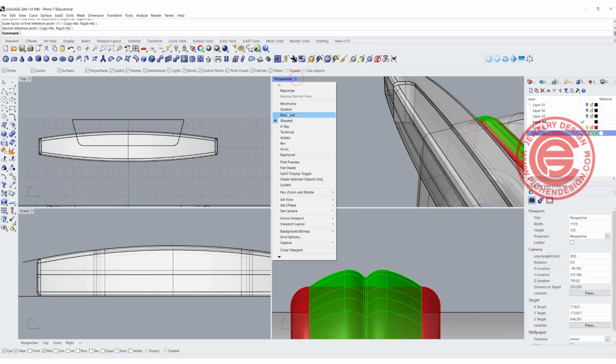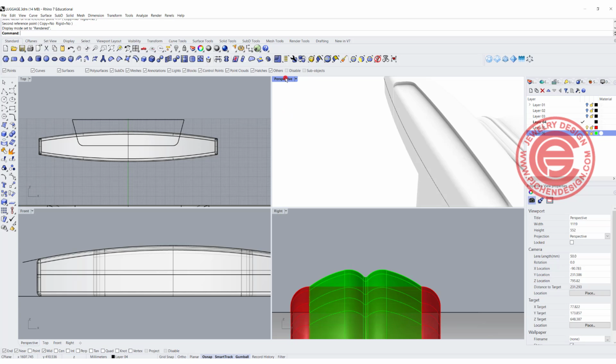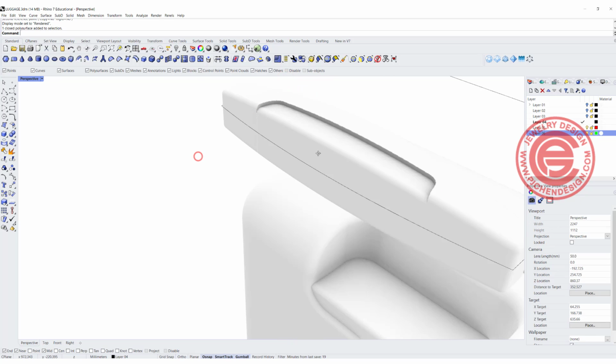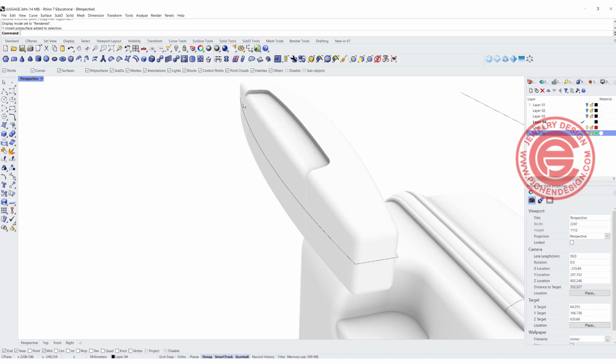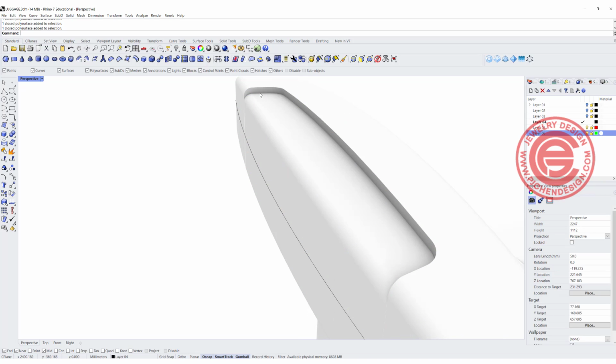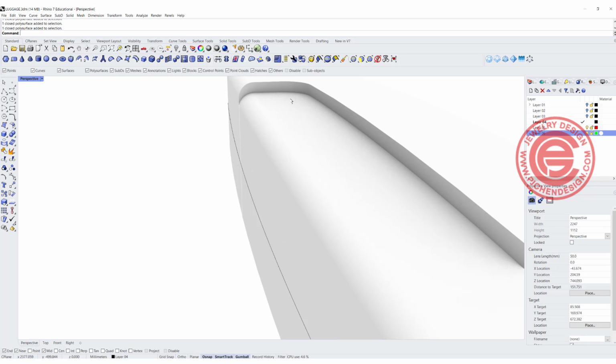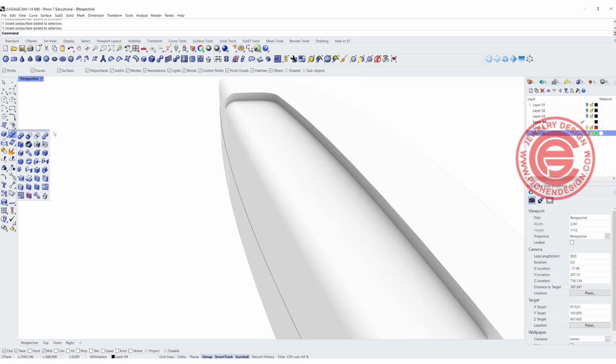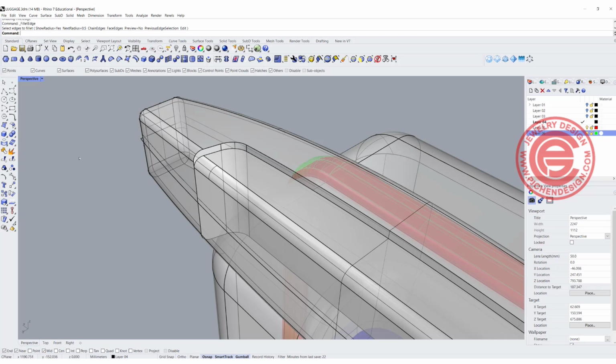If you take a look at the render view, you're going to see that I got more of the layers, and it's up to you if you want to assign them to two different materials. If you do, I would suggest you fillet the edges because it will look much nicer. Let me show you what I mean, even with something really small. So let's try radius 0.5 on this big one.